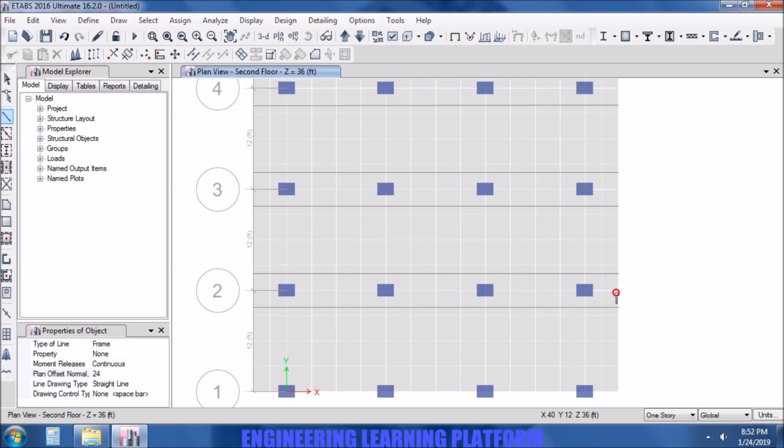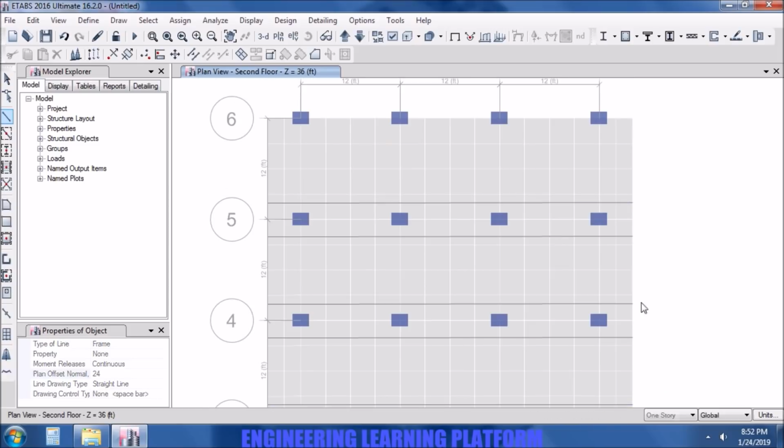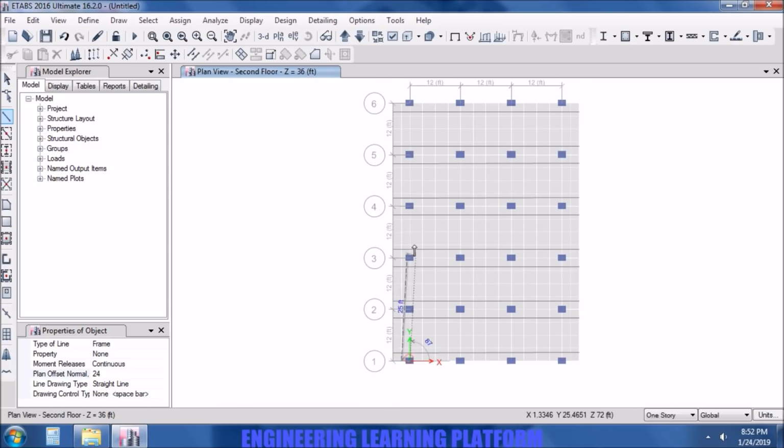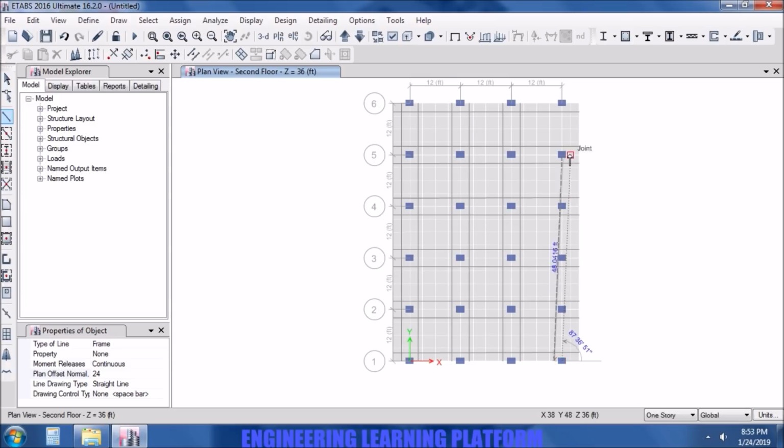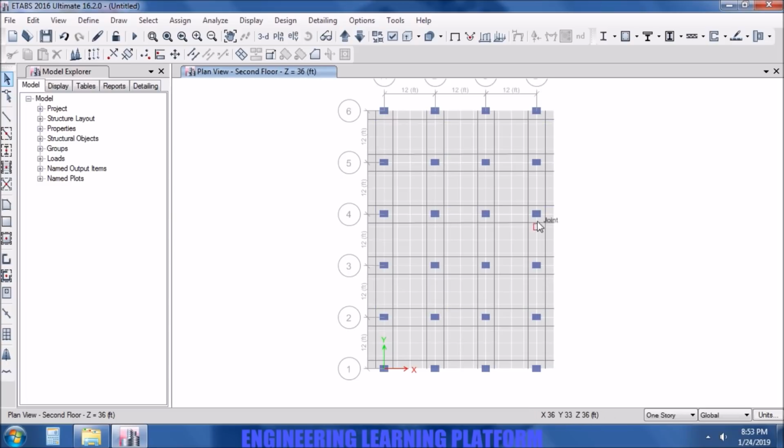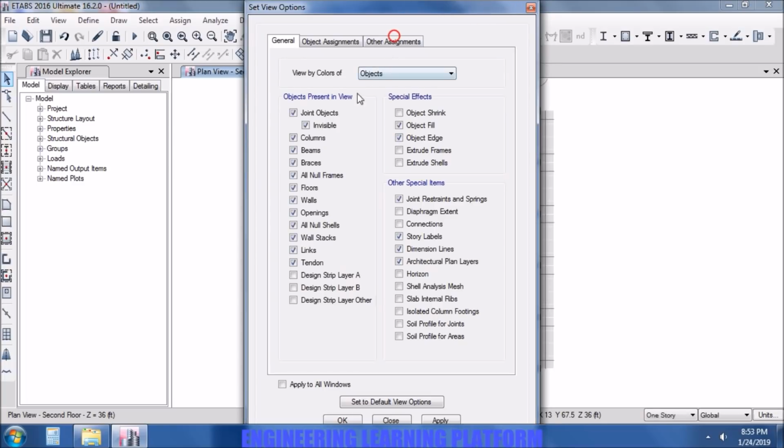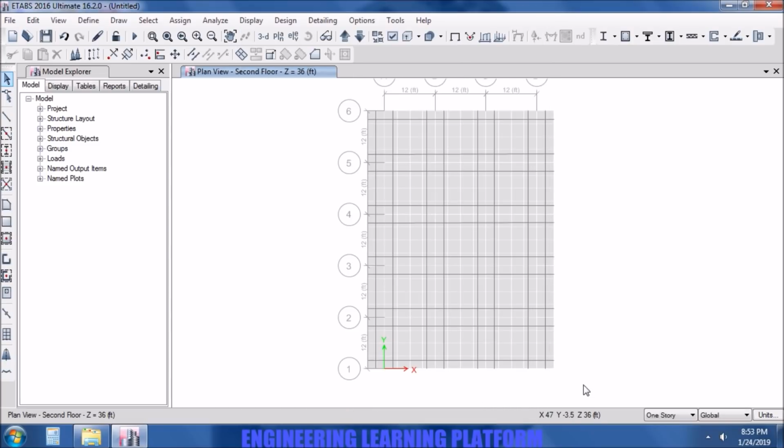Which is having an offset of 24 inches. So we are done doing it in y direction. Now we have to do the similar thing in the other direction of the axis, so that we have a complete set of drop panels formed by the intersection of these lines. But before that, you have to select the slab as a whole and match the slab at these lines, so that we can delete the areas between these lines for the drop to be drawn between them.